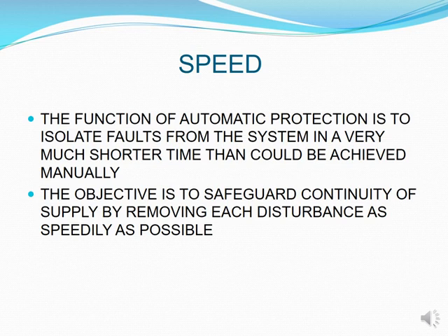And what would happen if you do not remove that fault or disturbance as soon as possible? It simply means that you could end up causing major damage to some of your major equipment. And that's what you need to try and minimize. Because remember, what we had said about protection is that it needs to be able to remove it as speedily as possible so that you minimize the damage, number one, to the point where the fault has occurred, in order for you to be able to do repairs that are going to be minimal.